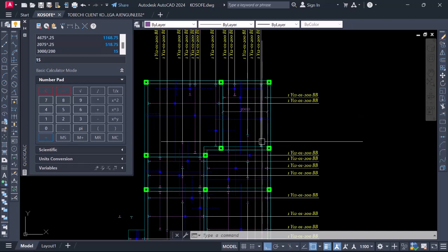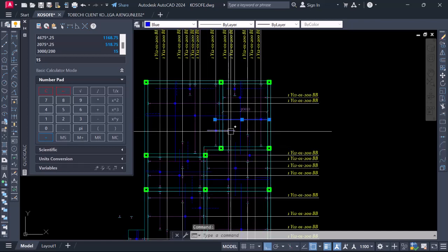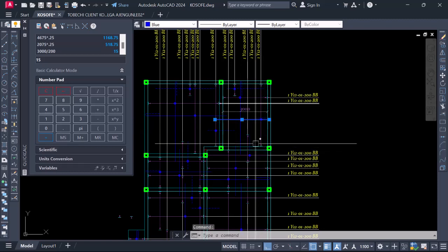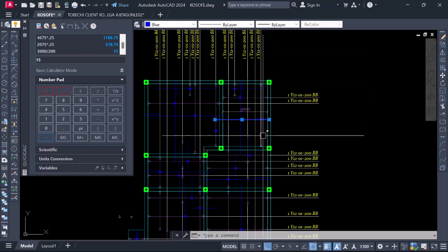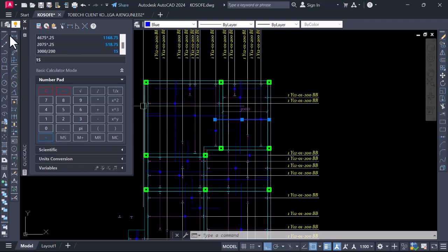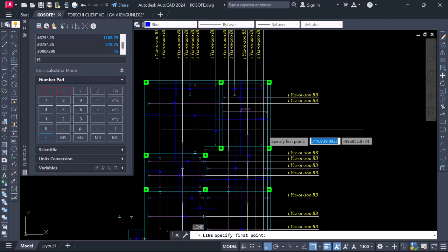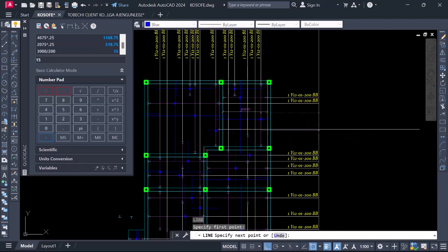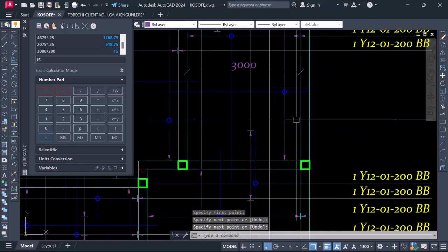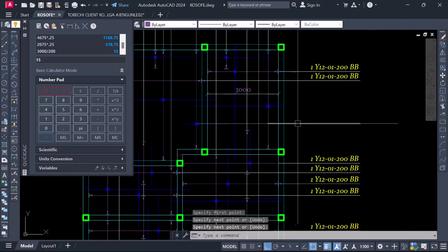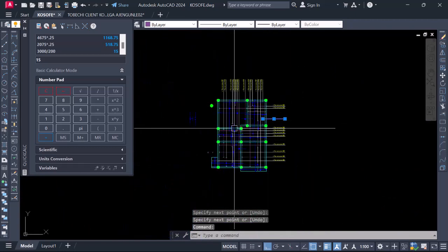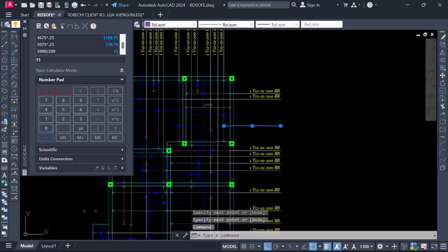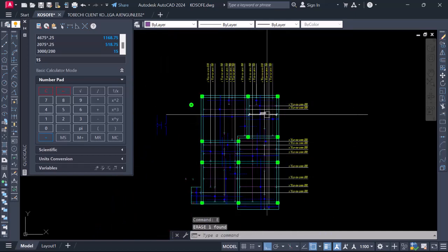This reinforcement is running from this span down here, so channel the label in this direction. I see some people will call out a label like this and create an arrow here. It's not bad, but always try to avoid that unless you have a clumsy detail. So let's try to keep it simple.